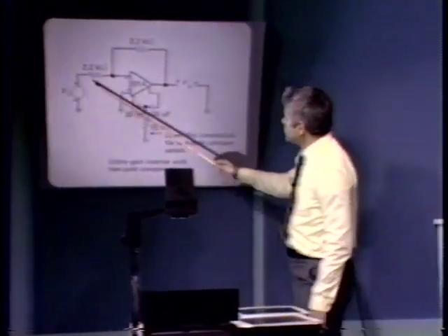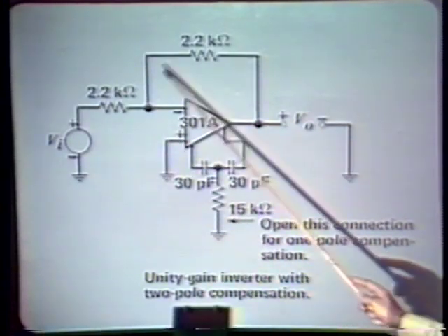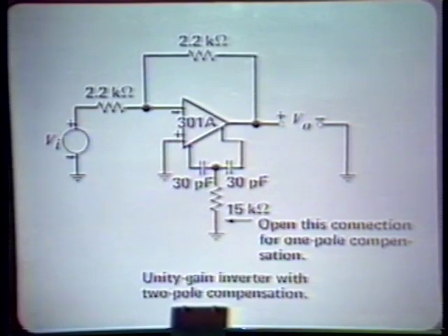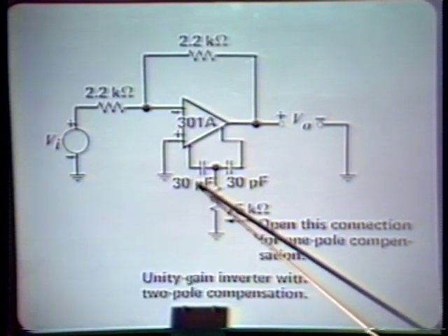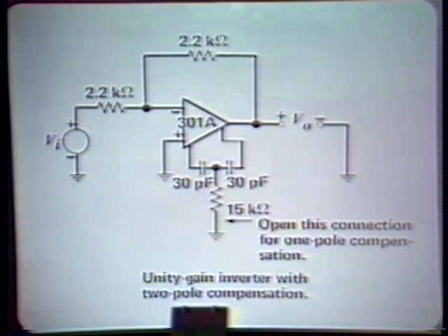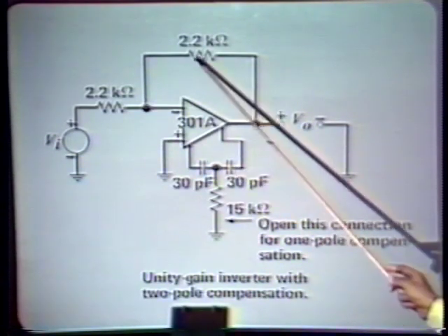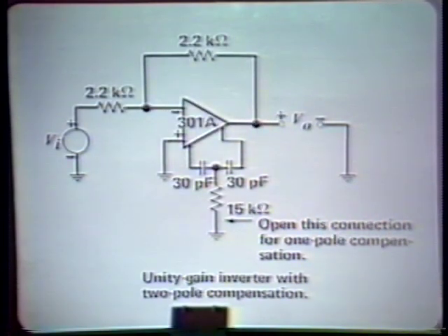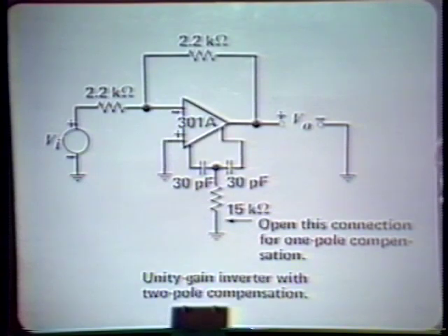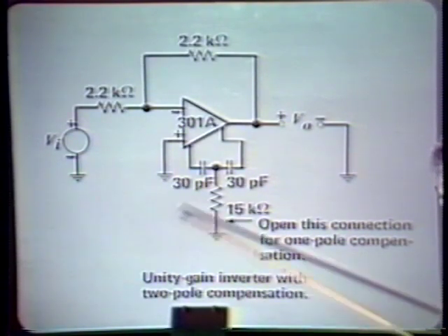Here's the configuration. We simply have an equal valued input and feedback resistor. We have the T network that does compensation. In this case, we chose elements in the T so that unity gain frequency in the amplifier is about 1.5 megahertz. The 2-to-1 attenuation provided by the feedback network forces overall crossover at about 1 megahertz or something like that.